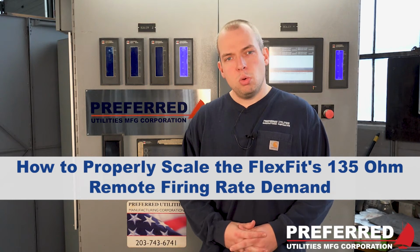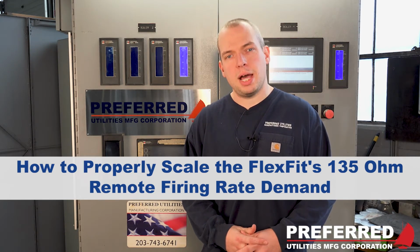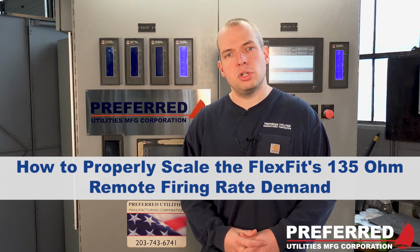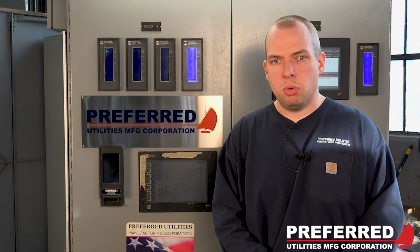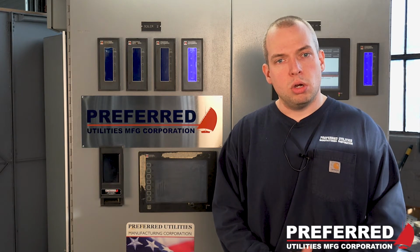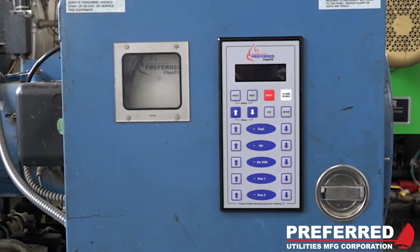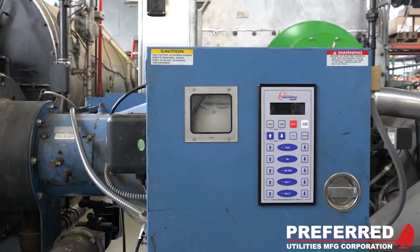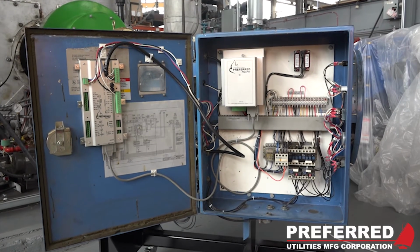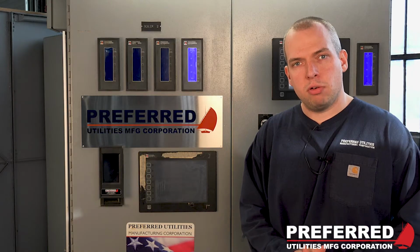In today's video, we're going to show you how to use the remote firing rate demand 135 ohm calibrate feature in the FlexFit combustion controller. 135 ohm firing rate control is not the most accurate when it comes to fine-tuning your firing rate demand signal. With Preferred's FlexFit combustion controller, we've added a calibration feature for the 135 ohm firing rate that allows you to dial in your 0% and your 100% remote span to get a more accurate signal.